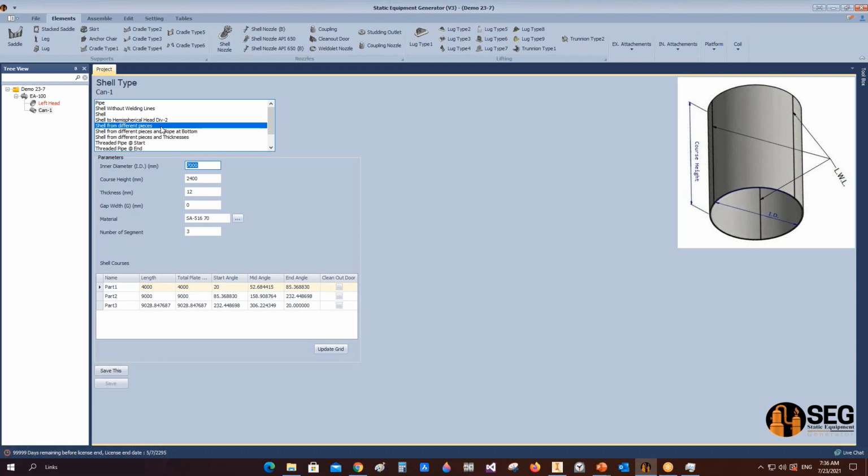Because in storage tanks we need to calculate the number of sheets per course. In storage tanks, one course may include a large number of sheet plates, and we need to reflect each sheet plate of those in the bill of material. And we need to control the length of each plate of those.